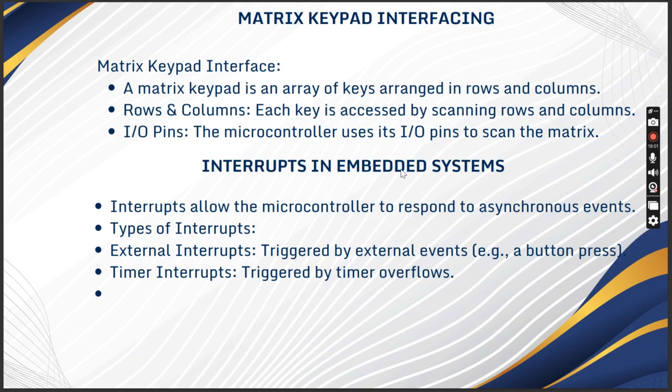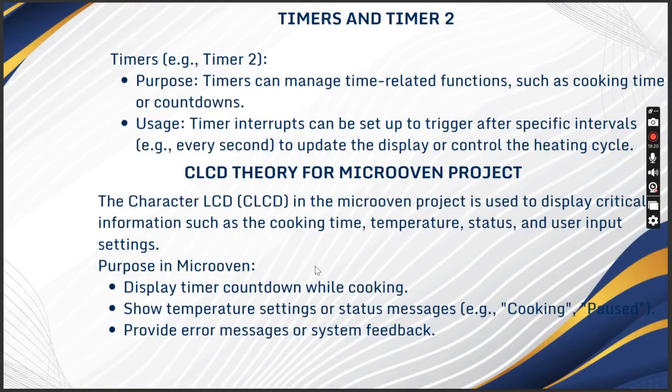Next is interrupts in embedded systems. Interrupts allow the microcontroller to respond to asynchronous events. What are the types of interrupts? External interrupts and timer interrupts. External interrupts are triggered by external events like a button press. Timer interrupts are triggered by timer overflows.